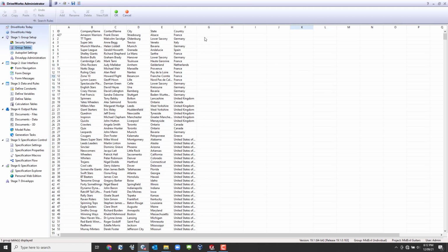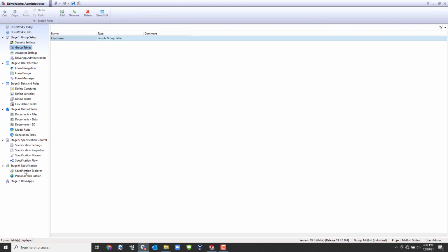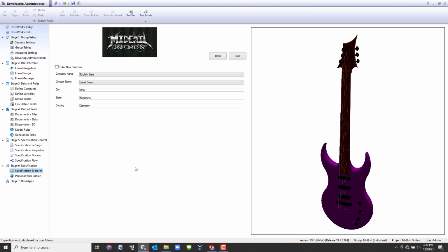Because he's got to spray this thing 15 coats or something, it has to cure in between, and then get wet sanded in between to get that gloss coat on it. To the point where if you're doing this a lot like they do, they have a UV bake oven to get this thing out the next day. Because otherwise, each coat can take 7 to 10 days to cure before you can sand it, right? So the time to market is all about paint for the guitar.